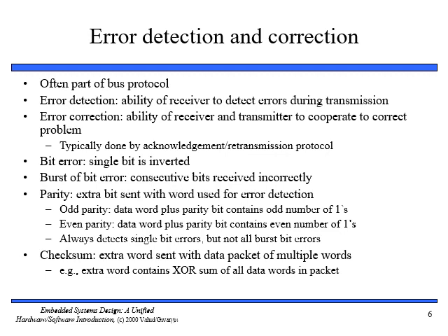Odd parity is a bit that, if set, indicates to the receiver that the data word bits plus the parity bit contain an odd number of ones. Even parity is a bit that, if set, indicates to the receiver that the data word bits plus the parity bit contain an even number of ones. And prior to sending a word of data, the transmitter will compute the parity and send that along with the data word to the receiver.